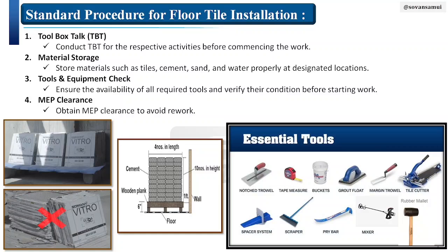We make a platform around 6 inches from the ground floor and 1 feet away from the wall. Okay, this is the right way to stack those materials.